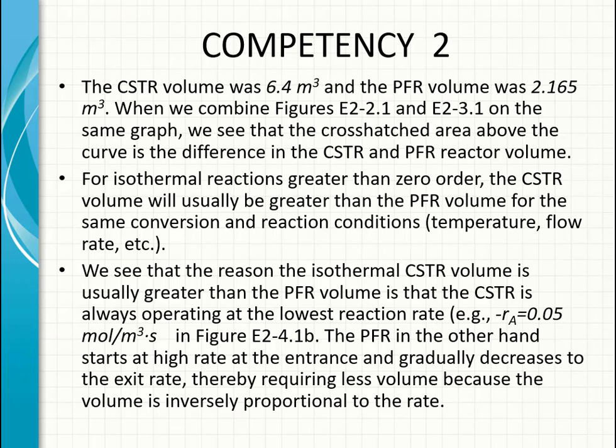For isothermal reactions greater than zero order, the CSTR volume will usually be greater than the PFR volume for the same conversion and reaction conditions, which are temperature, flow rate, etc.